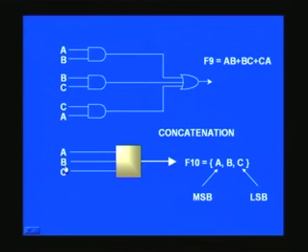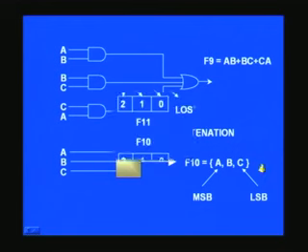Any digital node is a signal, and whatever IO you have in your system is a signal as such, and as usual you can assign this final output to any other signal name that you want, and let us say when you do this, it implies this A is in the MSB. So, always left side will be the MSB in all the treatments here, and naturally it follows suit. I mean the last bit is the LSB.